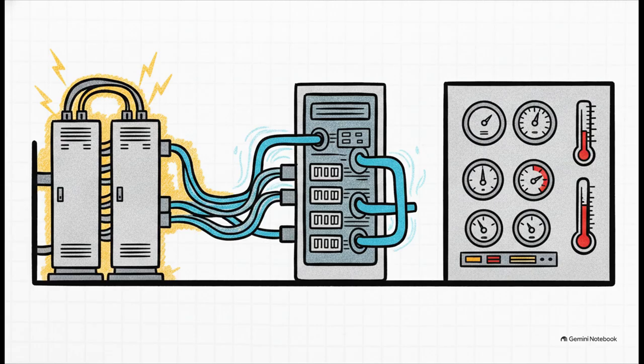If you were to walk inside one of these massive buildings, you'd quickly realize the actual computing is the smallest thing happening in there. The building is fundamentally a massive electrical panel and HVAC system, built specifically to keep the machines from overheating. You've got an electrical system drawing megawatts of power, mechanical systems featuring industrial liquid cooling radiators bolted right onto the chips, and a control system with thousands of sensors monitoring the temperature around the clock. Because every single watt that comes in as electricity leaves as heat, and managing that heat is basically the facility's main job.